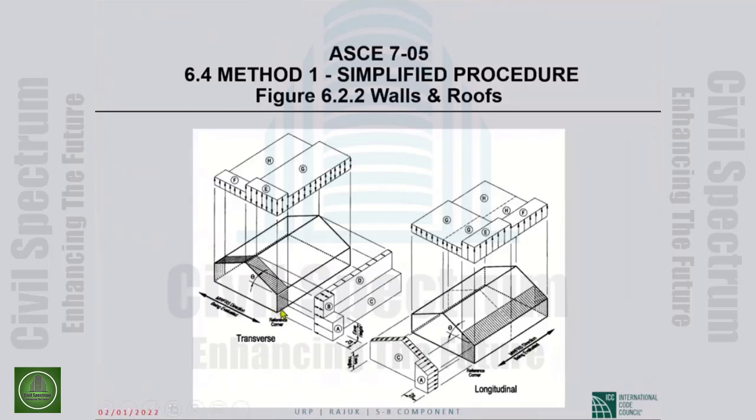And the method tells you each corner of the building shall be taken as the reference corner in turn. If a building is doubly symmetric, then this turning is going to be unnecessary. You will get the same pressure distribution no matter what. If it is singly symmetric, you will turn it once and you are done. You will have all the information you need.